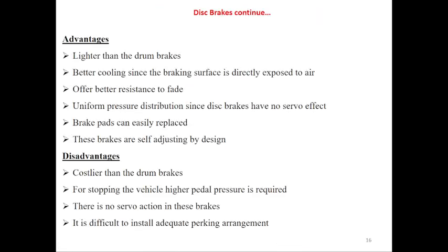The disc brake has some advantages and disadvantages. First we see the advantages. The first advantage is that it is lighter than the drum brake, so that's why we reduce the weight of the total vehicle and increase efficiency. Then better cooling, since the braking surface is directly exposed to air.